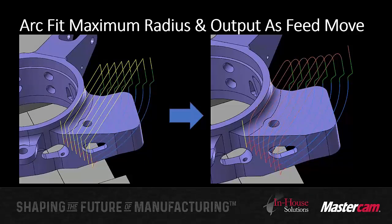Now, one of the features that I utilize all the time now is arc fit at a maximum radius and outputting as a feed rate. If we're doing numerous parts and we're really trying to trim out the time, rather than just having it wrap it up, wrap it over, wrap it down, I can choose to have arc fit a maximum radius. On the right-hand side, you can see that rather than having just a couple of linear moves, I actually get radiuses input in my X, Y, and Z just to trim out that time.